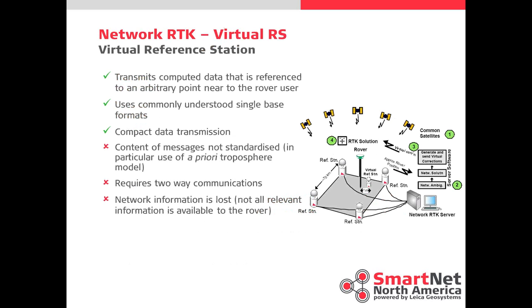With a virtual reference station, like I said, it's been around a while. When it was initially introduced back in the late 90s by Terasat and then acquired by Trimble, it was a really good solution because of the lack of power on the rover. It being server-side processing allowed the rover to be much lower powered as far as its computational processes, which, if you think back 10 years ago, how far we've come in miniaturization and processing power on the rover side is pretty amazing.